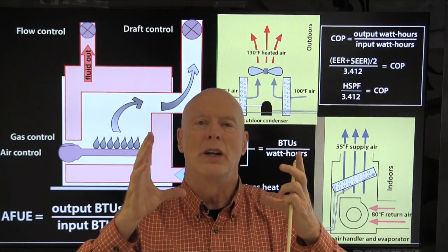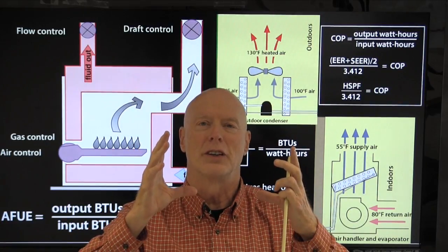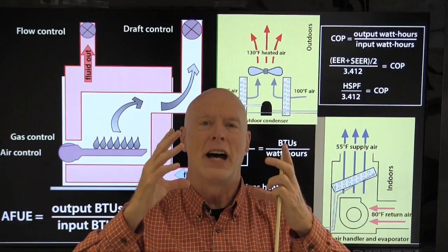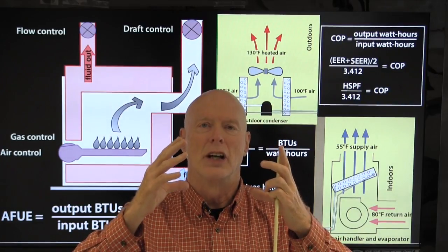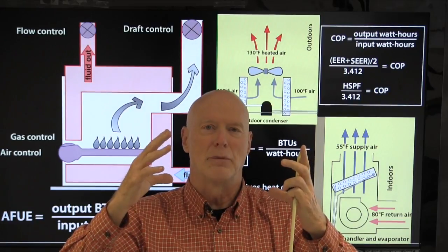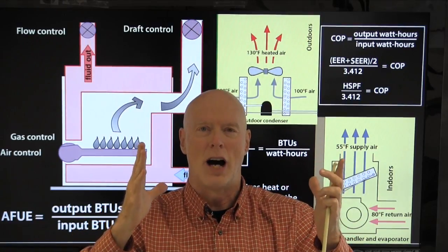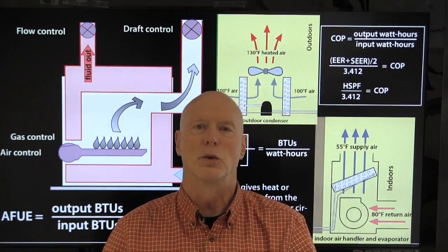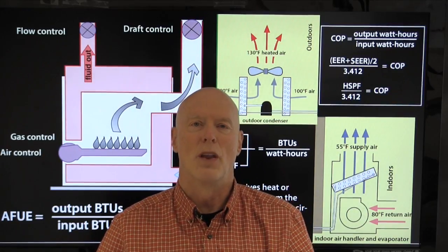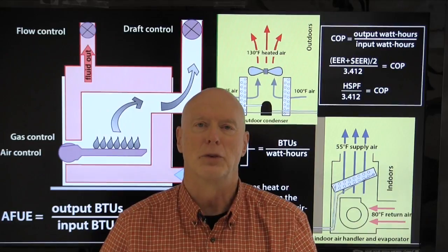And then when the thermostat turns the system off, that heating or cooling heat exchanger changes its temperature, and energy is lost with each one of those cycles. That's one of the major losses that we're dealing with, one of the major problems with efficiency.